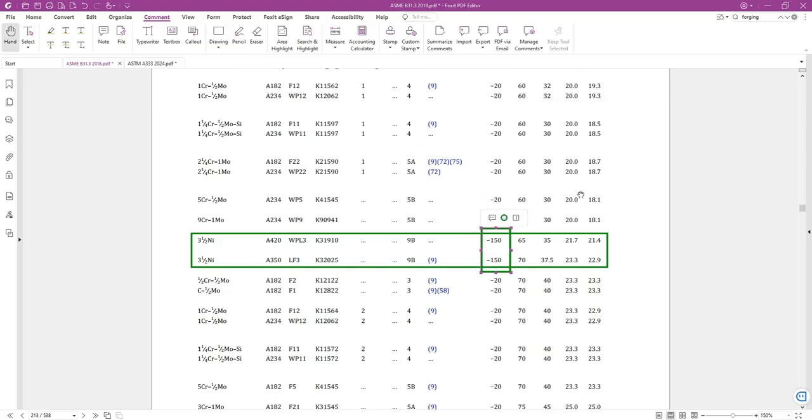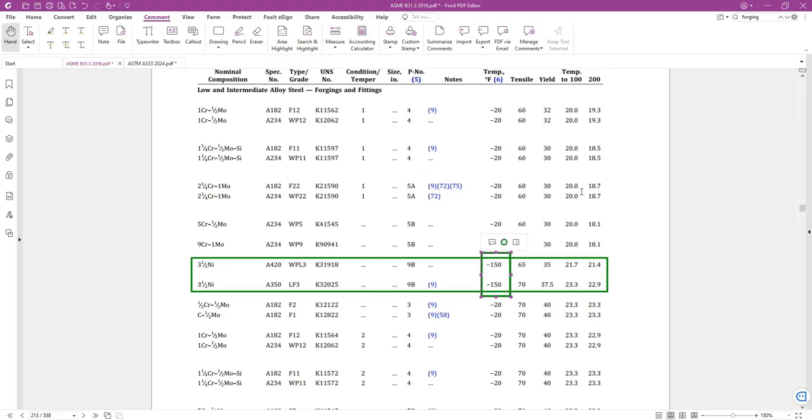As I told you previously, if it is not possible for you to procure these materials for your project, you can use other materials with minimum allowable temperature warmer than the process minimum design temperature, either with or without impact testing. For checking whether impact testing is mandatory for your case or not, you need to read and understand Chapter 3 of ASME B31.3. Then you may use the exemption conditions for your scenario.